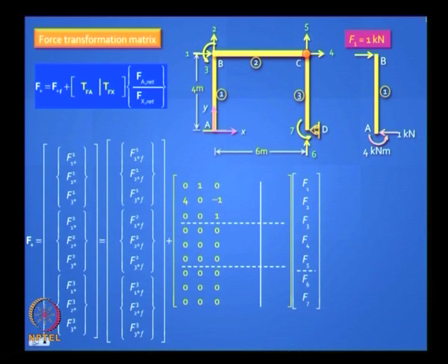You will find that the first item here, what does this correspond to? What does F1 star correspond to? Axial force. Will there be any axial force in this element? No, that is why I put 0 there. Second element corresponds to what? Moment at this end; it depends on how you put your element, but it's 4 here, right? And the third one, moment at B, is 0, right? It depends on start node, end node. I put start node at A, so anti-clockwise is clear, so it's 4.